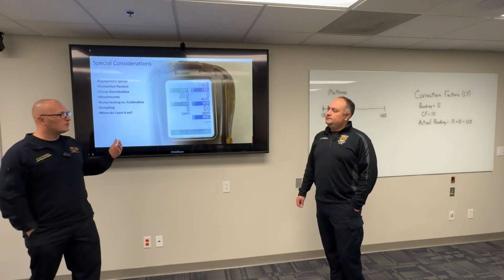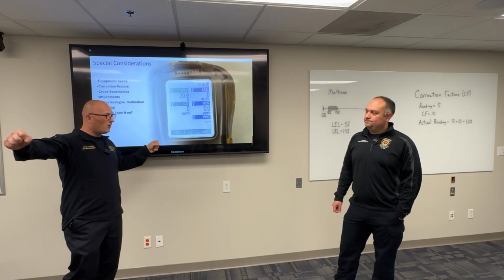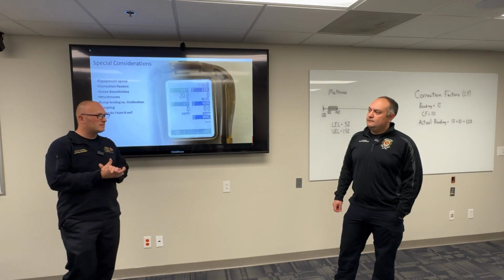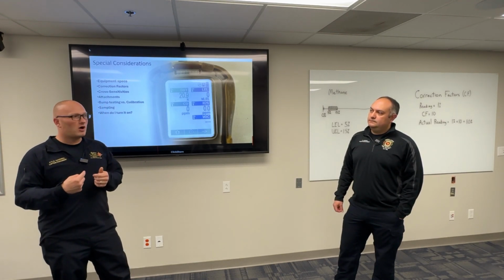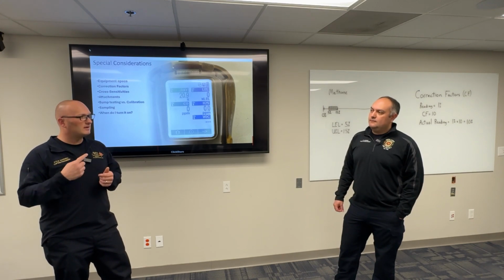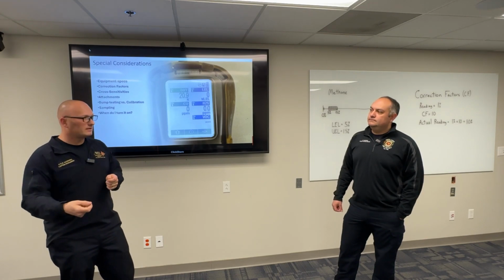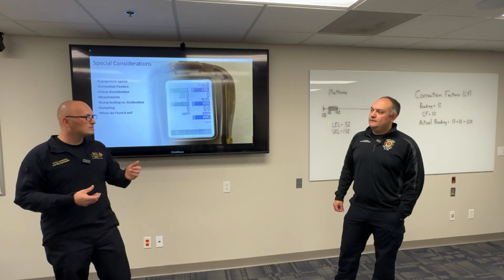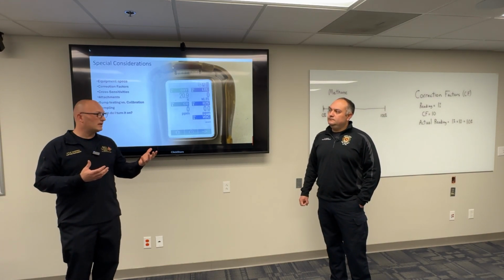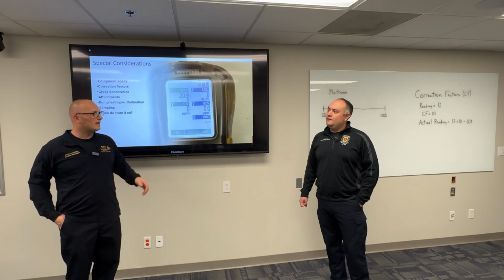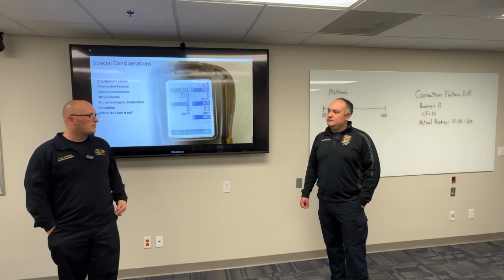Our attachments, those are big. Most of the Ray products come with the long wands and the tubing and all that stuff. MSA, I'm sure they have the same stuff. But just remember, when I'm using attachments, it's going to take a little bit longer for that gas to get into that meter and that pump to get it up there for you to actually get your readings. So I can't just dump this down here and say, oh, I got nothing, and pull it back out. It's going to take some extra time. So by playing with these meters, know how long that's going to take. If I put something down in a sewer, I need to know how long it's going to take for those readings to come back up.